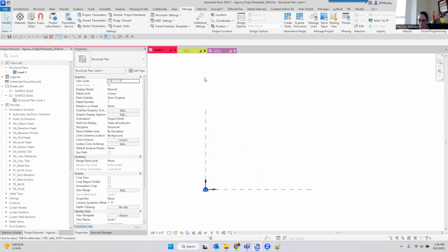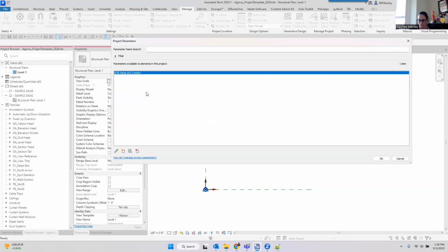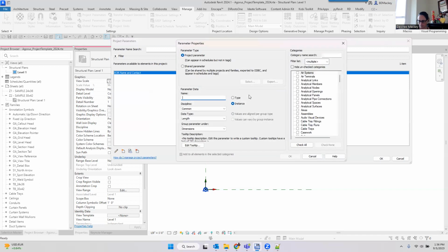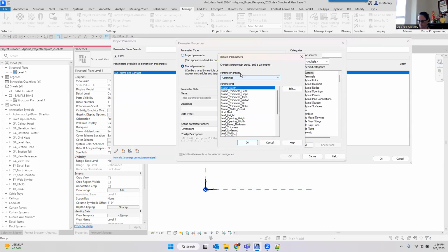Sorry, when I go to add this, I've got to add a parameter. I'll change that in my file. And here's why. When I go to add it as a project parameter, or if I'm in a family and I'm going to add it as a family parameter, and I say I want to create a new parameter, I want it to be a shared parameter, and I have to select, it'll dump me into that group. So renaming the grouping becomes really, really nice. I've got to add 10 of these, but like I said, inside of here I can't grab more than one.